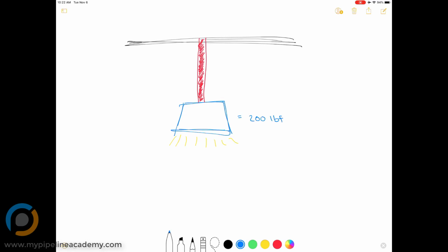And just because it starts plastically deforming doesn't necessarily mean it's going to fail, but it is well on its way to failing if it starts plastically deforming. And there's a good chance it will fail. Because if I understand correctly, once a material starts undergoing plastic deformation, then less stress is required to continue the deformation. That's true. Yep, that's true. So I guess if you have a constant load on it, like we would with this light, it would end up failing if it reaches that plastic deformation. Could be months though, depending on how close it is. Actually, it probably wouldn't be months. It would either fail pretty quickly or it wouldn't.